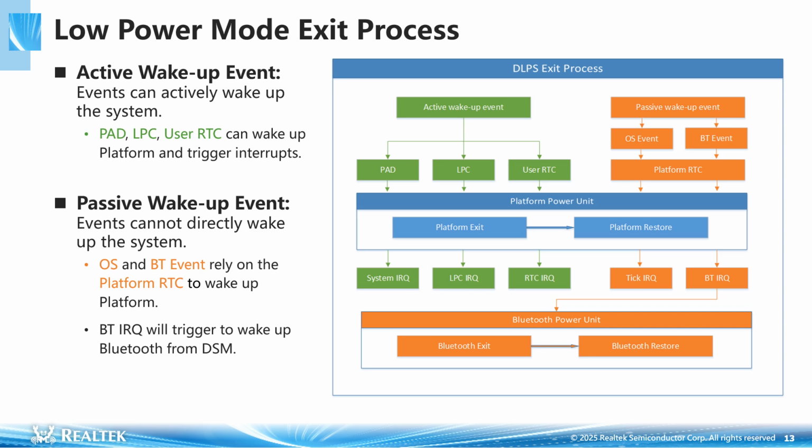Passive wake-up events cannot directly wake up the system. Instead, they rely on the platform RTC to wake up the platform. These events include OS and BT events. Additionally, a Bluetooth interrupt will be triggered to wake up the Bluetooth module from DSM, deep sleep mode.